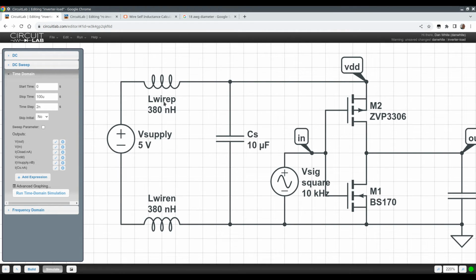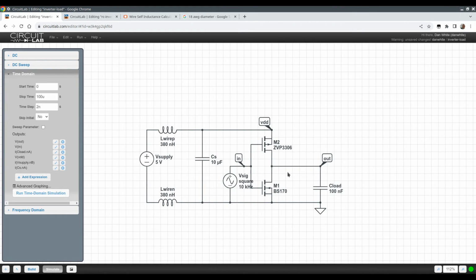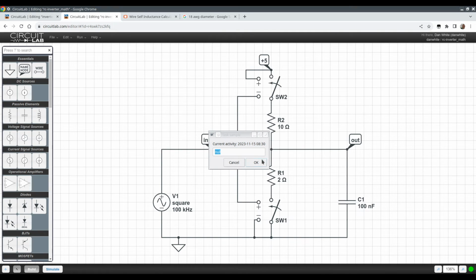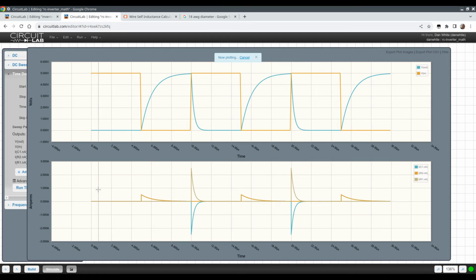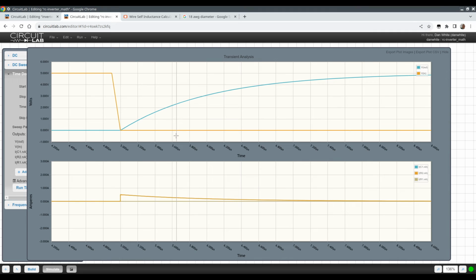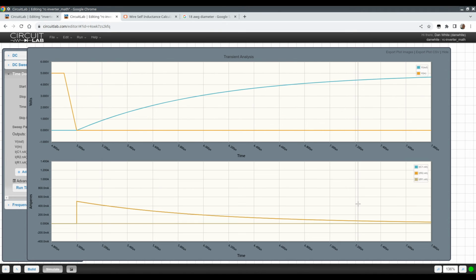Simulate these around. These wire inductances are actually probably a little low. Shorter wire. Okay. I have one more circuit here. This is a voltage controlled switch that LT Spice has. This is the same setup. These numbers are approximate on resistances from the data sheet. Simulate this thing. Well, howdy doody, I get the same behavior for the rising edge and the falling edge. But what I really get, I want you to pay attention closely to the current on here on the lower one.